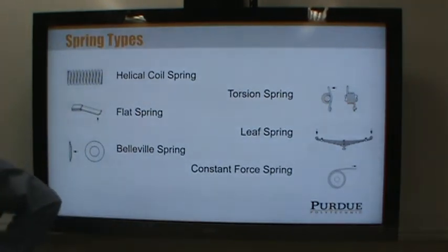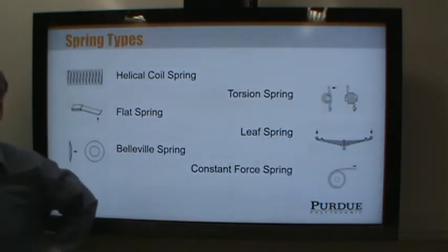Anybody ever seen this used in an industrial environment? Right. We've got one that's set up as a counterbalance on our ceiling. Okay. So it's basically applying constant force to the top of the ram to support it so that the motors don't have to lift it. So it's kind of like a garage door, but with a constant force spring instead of one that varies. Yeah. Okay, all right.